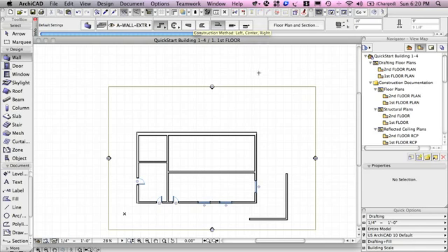And we've looked at how you can draw a wall that starts from the inside or the outside when you are drawing. In most cases, it will automatically just intersect or connect it. And some of the smart cursor options for showing a wall and how it's about to touch another wall and connect perpendicular or at another angle. And then we've looked at both the adjust and the intersect options for connecting walls together.